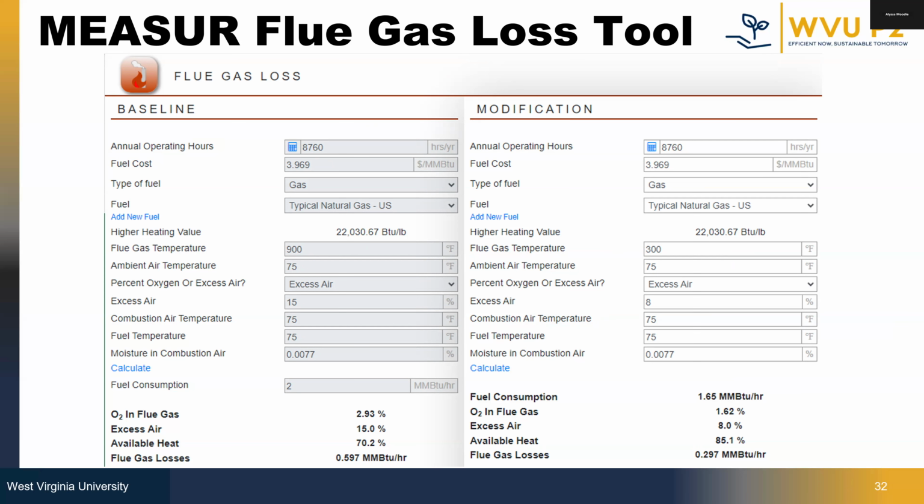So an increase in emissions means that the fuel is not combusting completely due to insufficient air. So if we find that point where the excess air is as low as we can get it and the emissions are under control, then we found the optimal position.